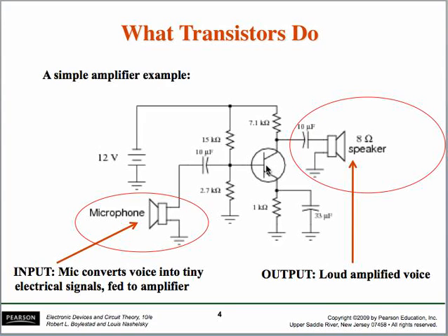What is it? Yes, that's right. It is a PNP transistor. How do you know? Because the current at the emitter here, this is the emitter terminal, the direction of the arrow is pointing in. So that's why it is a PNP transistor. Now let's see how the transistor works in this circuit.